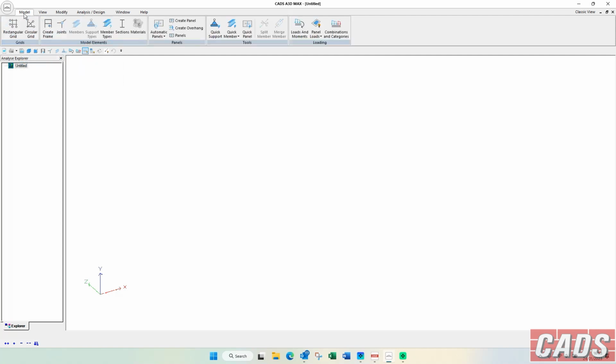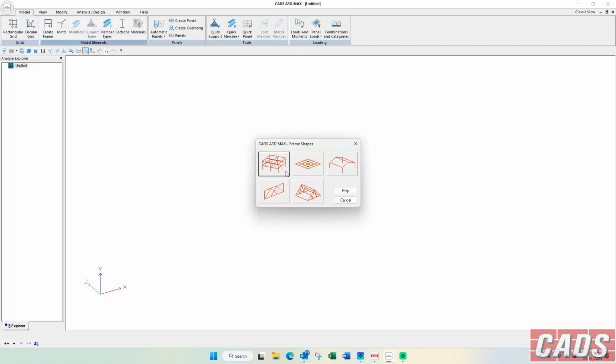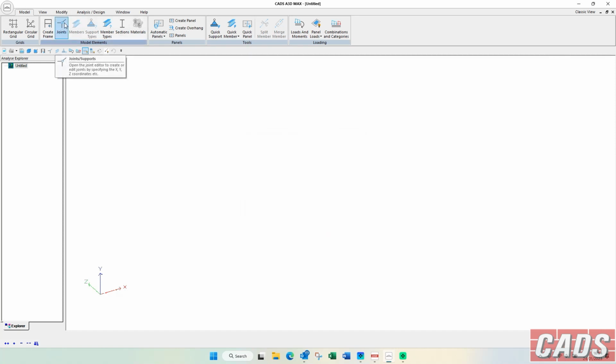But just going from left to right, we've got the modeling. I'm going to show you how this works, but this is just a sort of go round first. This is grids, which you can bring into the screen to put your members on, circular, rectangular, and they can be connected together. We've got some wizards for multi-bay frames, grillages, portal frames, trusses and girders. You can obviously type in individual nodes if you want to and join them up with the mouse. Put in member types, steel, concrete, timber, for instance. There's a variety of materials which we offer you, but you can edit